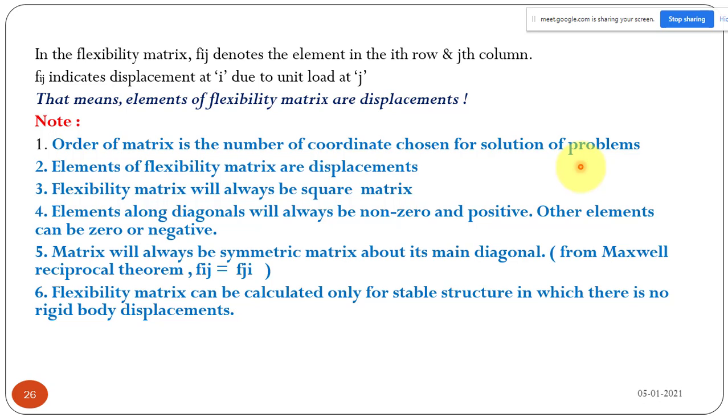That is why when you are going for a highly indeterminate structure, your manual calculation will become very difficult, because if you have 20 extra unknowns, static indeterminacy is 20, maybe your matrix order will be 20 by 20. That will make it difficult when you come to manual calculation. So that is why we have to put everything in the software so that it can be solved.